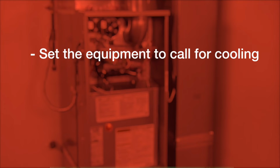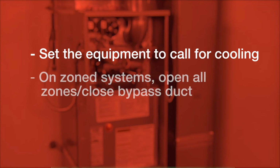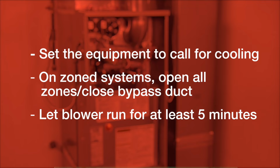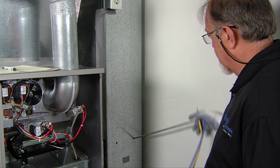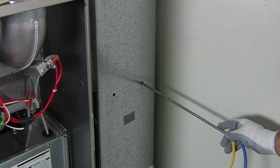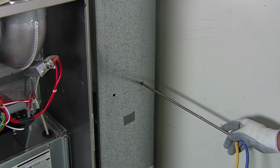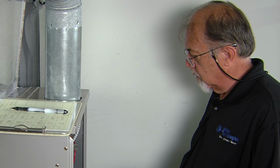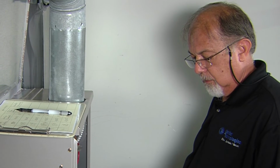Set the equipment to call for cooling at the thermostat. On zone systems, open all zones and close the bypass duct. Let the blower run for at least 5 minutes to allow the airflow in the system to stabilize. Insert the Pitot tube into the hole in the duct. Make sure the Pitot tube is level and the port is pointing up as you take each reading. Record each Pitot tube reading on your data sheet.